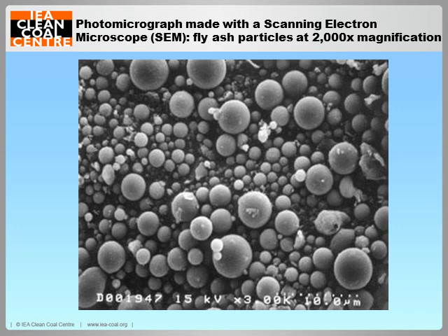Fly ash, which constitutes 85 to 90% of the overall ash, is a fine, light grey powder made up of glassy spheres from submicron to more than 100 microns in size, 98% smaller than 75 microns, 70 to 80% smaller than 45 microns. Fly ash is suitable for utilization in industrial applications. Its constituents depend upon the specific coal bed makeup, but may include one or more of the following elements in quantities from trace amounts to several parts per million. These are arsenic, beryllium, boron, cadmium, chromium, cobalt, lead, manganese, mercury, molybdenum, selenium, strontium, thallium, and vanadium.